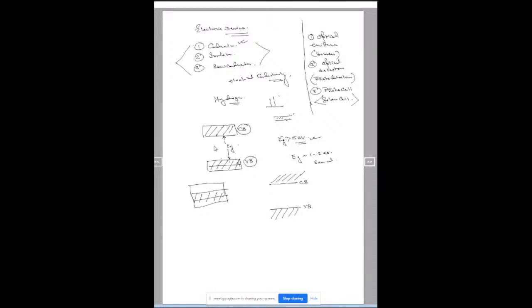So for the valence band, when we draw a line, we are actually implying that this is the top of the valence band, and this is the bottom of the conduction band. These two lines, representing the bottom of the conduction band and the top of the valence band, are very, very useful in describing the transport of charge carriers, in particular in semiconductors, right? This kind of diagram is called an energy band diagram.